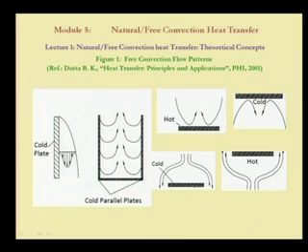And in this case, this is the cold surface, and this is another way of looking at these circulations. If this is a cold surface, the material will get cooled, and the surrounding fluids are at a higher temperature. Once they come to the cold surface, they get cooled and try to go in the downward direction. Similarly, at a hot surface, the fluid element will come and try to go in the upper direction. This is the way the flow of the fluid elements will take place.